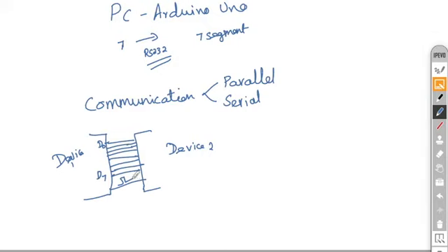So what it means is whenever the clock is triggered, at that time the data will be transmitted from device 1 to device 2 or device 2 to device 1. So the information exchange will happen only at this trigger point. At one trigger itself, 8-bit information is transferred. For example, let us take a PC over here and a printer over here. This is the earlier parallel port; in earlier PCs it was used mostly for printers. For one clock pulse, one 8-bit information is transferred.